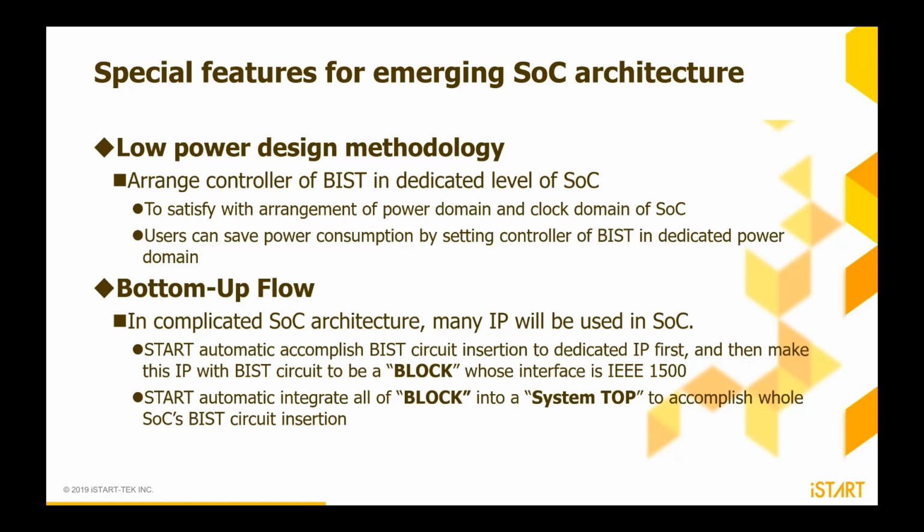Next is the bottom-up flow. In a complicated SoC architecture, many IPs will be used in the SoC. So use our bottom-up flow. You can insert your BIST and repair block by block, and you can also automatically integrate all blocks with the system top to accomplish the whole SoC BIST insertion.